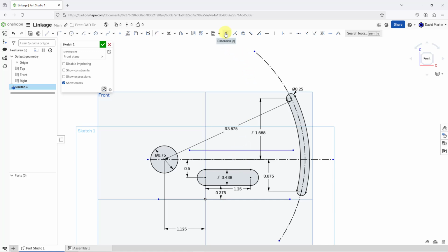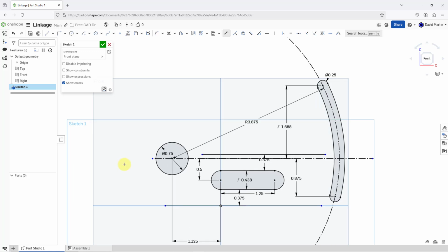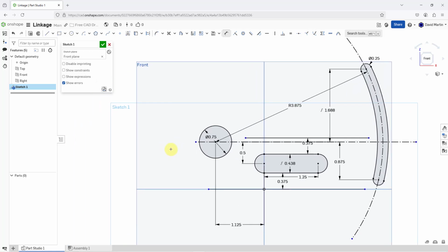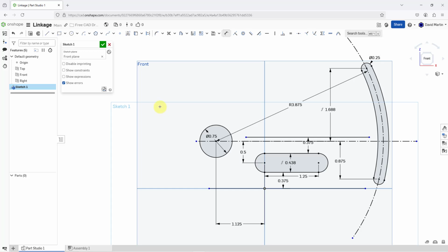So I'm going to throw it in right now. Let's dimension from here to here, and this is going to be a value of 3/8 or 0.375. Hit the enter key. Now that I've got those two lines, I can do the arc going around this area. I'm going to make a 180-degree arc around that circle on the left.